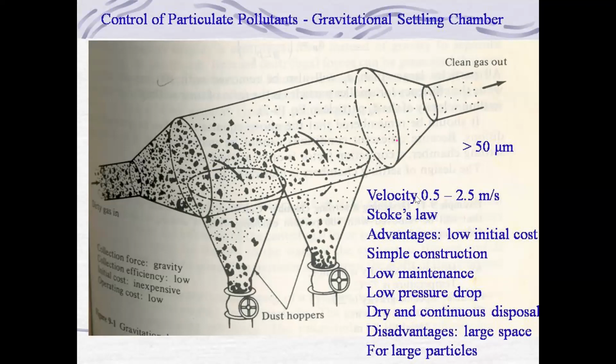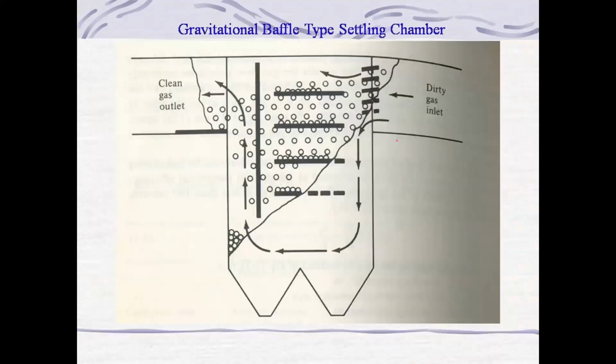Okay, so have you understood? May I repeat? The gravitational settling chamber is made for the collection of solid particles, or we can say particulate matter, from the laden gas, whose size is greater than 50 micron, and it is usually the first unit operation. Second, it is used for dry air applications. Wet air is not allowed here. So: dry air, particulate matter, 50 micron. These are the highlights of this particular equipment.